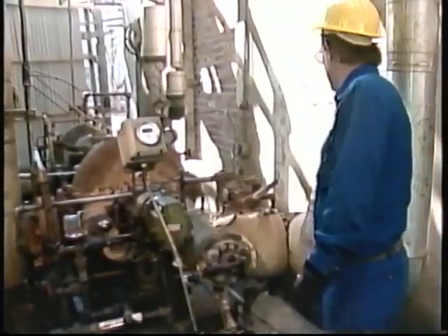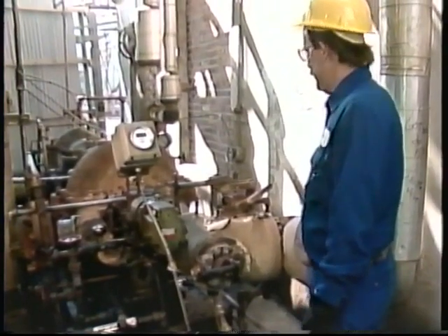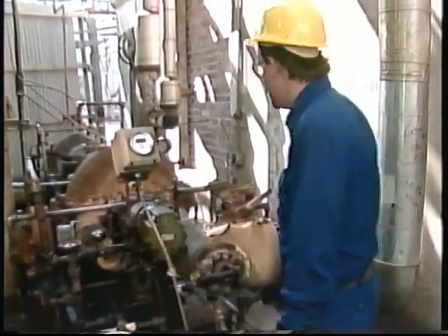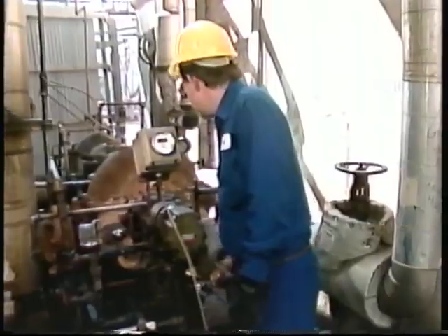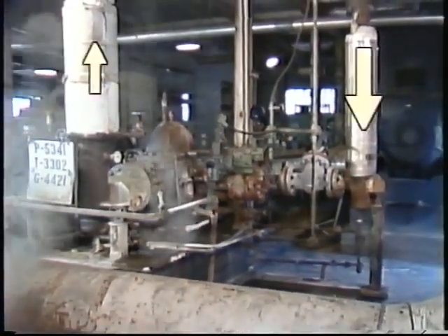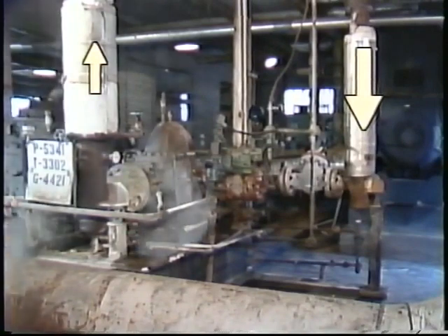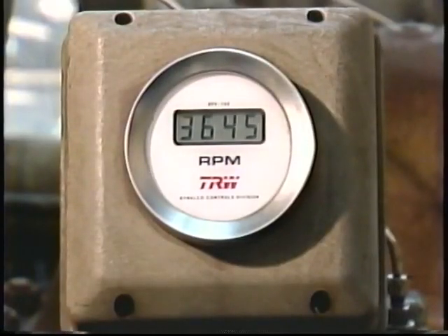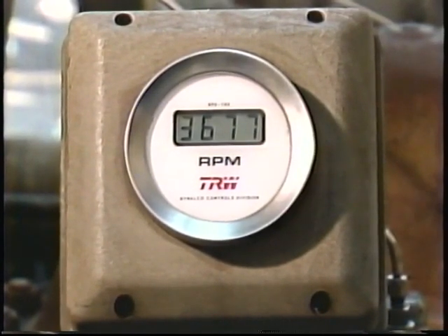In addition to low turbine speed being a problem, you may also be confronted with the problem of high turbine speed. A number of different causes, like high inlet or low exhaust steam pressures, for example, could make the turbine speed be steady but too fast. If you find that the turbine you're working with is running at too high a speed, tell your supervisor so the condition can be dealt with according to the operating procedures for your facility.